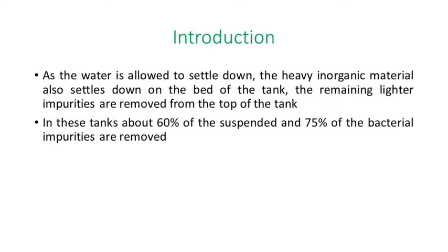Next, as the water is allowed to settle down, the heavy inorganic material settles down to the bed of the tank, and the remaining lighter impurities are removed from the top of the tank. The lighter impurities you can remove from the outlet at the top, and the suspended impurities which settle down at the bed of the tank you can remove from the bottom of the tank. In this manner you can remove the suspended solids from that water.